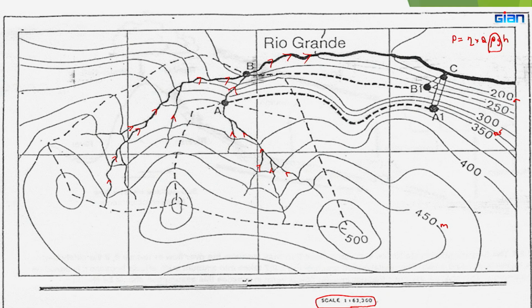Q is flow rate in cubic meters per second, H is in meters, the water head height difference between your diversion weir and the forebay tank level and your turbine level, right. So, that is what we are interested in hydropower, what is the height, potential energy is in the height. So, we want to convert that to power, which is in watts or kilowatts, right. It is directly proportional to Q and H, flow rate and head, right. Now, with this in mind, the hydropower engineer looks at this.